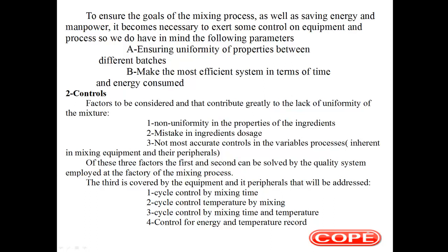Some factors should be considered for the lack of uniformity. The first one is non-uniformity in the properties of the ingredients. Second, mistakes in ingredients dosage. Third, not the most accurate controls of the process variables inherent to any mixing equipment and its peripherals.